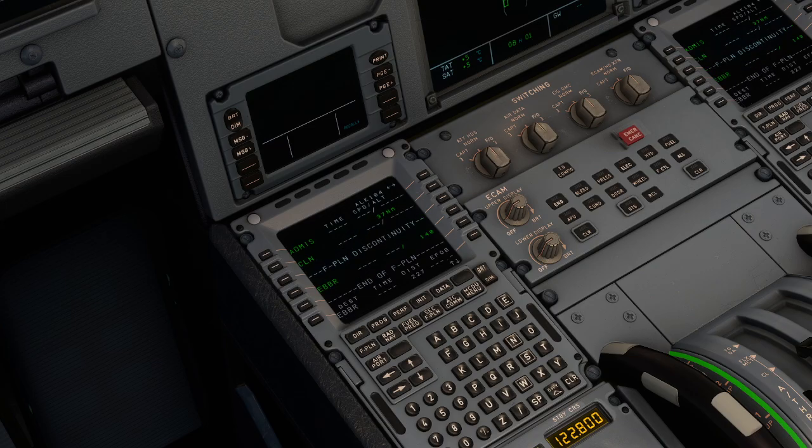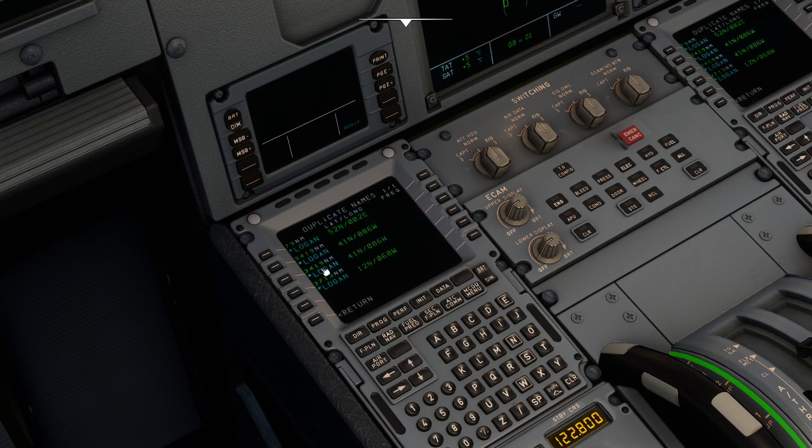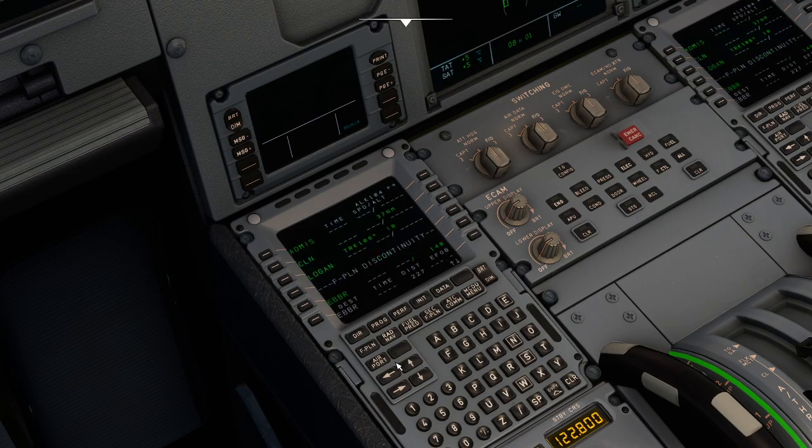And then I'm coming to Logan: Lima, Oscar, Golf, Alpha, November, LOGAN. And here I get four options. Wow. And I'm selecting the closest option at about 79 nautical miles, which is the closest one to our airport, so it is going to be the most accurate one.